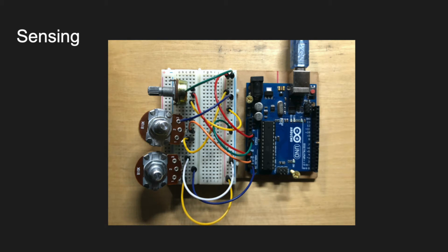Due to not having access to the structural engineering lab and active demonstrations of the sensors, we developed a hardware prototype using an Arduino Uno and several potentiometers. This setup is used to simulate data collection. The Arduino allows us to output 5 volts through a 10 kiloohm rotary potentiometer and read the data back into the Arduino serial ports.